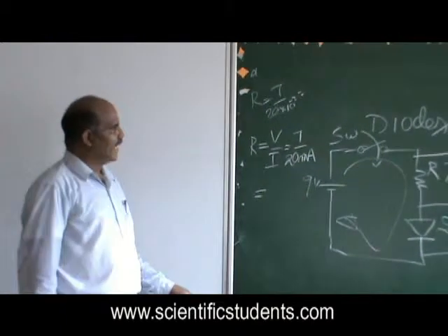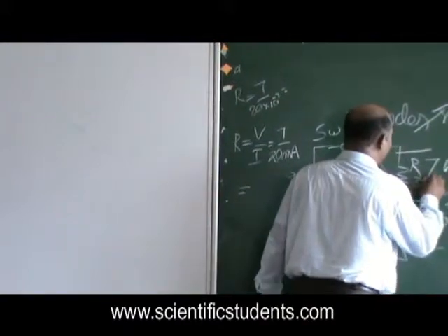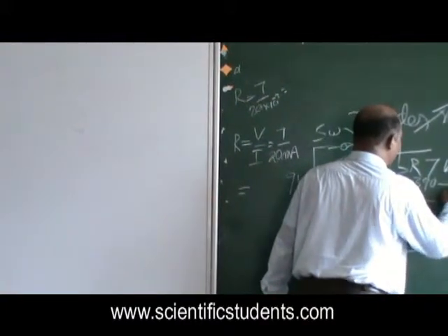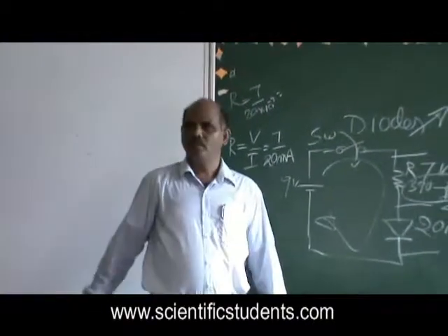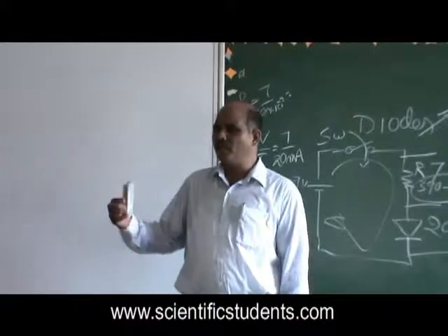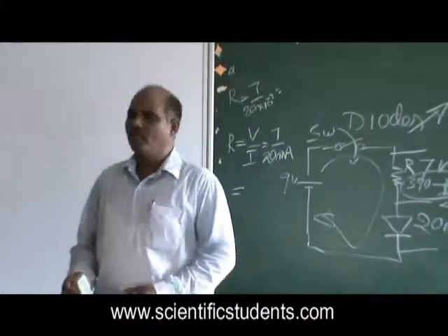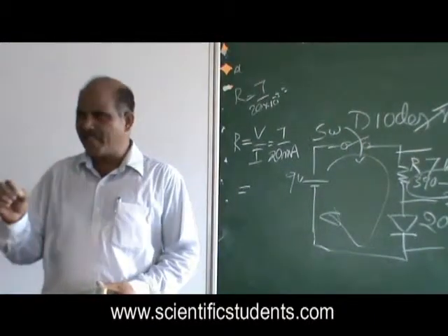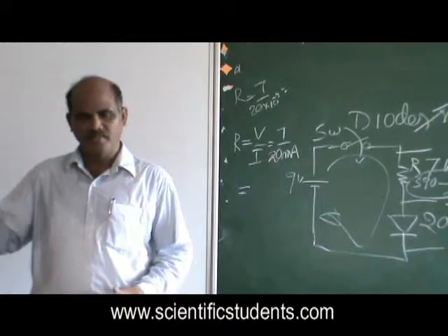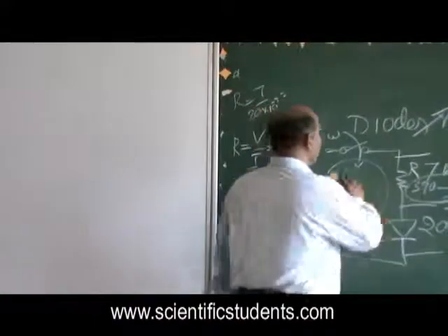So you calculate the value, and for a 9-volt battery it is supposed to be somewhere around 390 ohms to 470 ohms. Or even up to 1K, 1.2K, you can increase it, because I designed this circuit with 1 kilo. Why? Because at 1 kilo the brightness is reduced but the battery lasts for more time. Okay, then you finish it off, calculate the value.